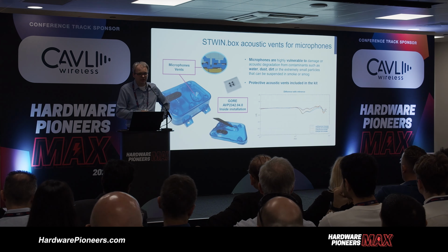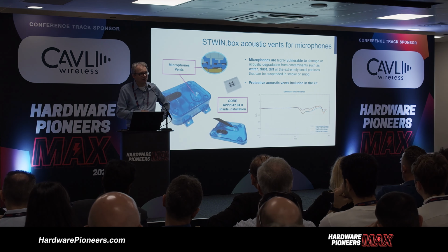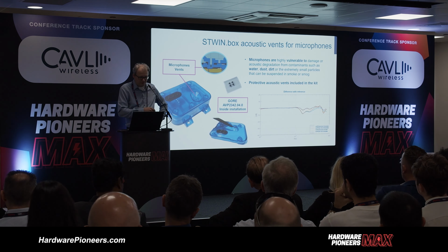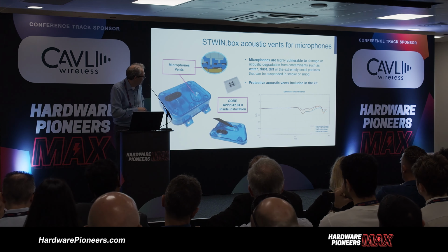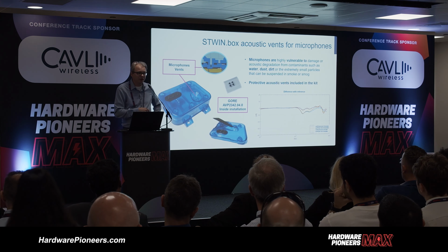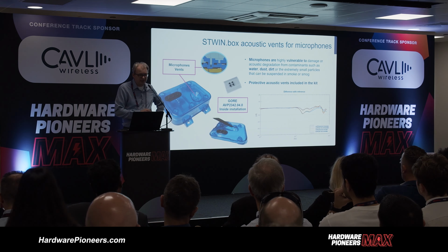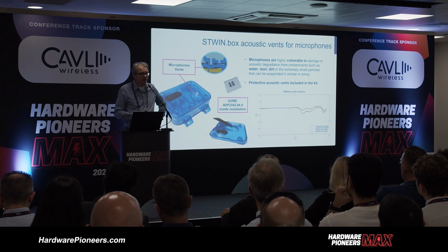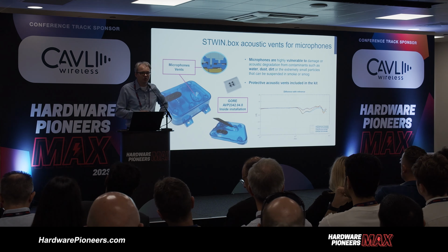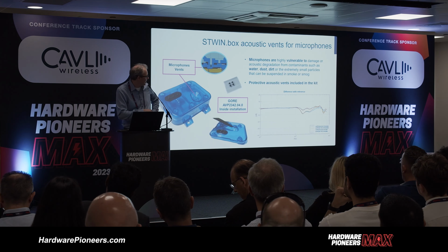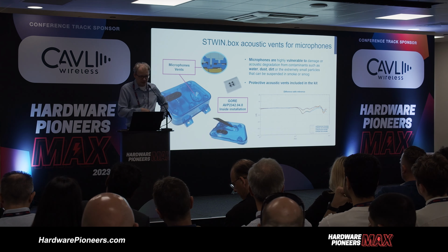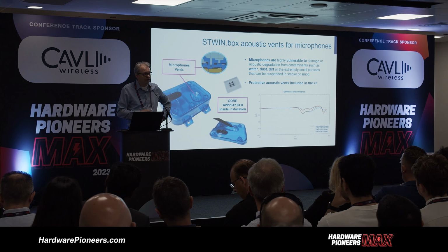Another new thing on this development kit is for the microphones and pressure sensor, that we included this kind of protective acoustic vents. These are coming from company Gore, so a bit similar to what you use in different kinds of fabrics. But what we did is that we measured this up to 80 kilohertz now and verified that it works up to ultrasound. So again, something that you would need to take into account in the final end product design to ensure that the dust and water is not entering all the way into your end product. And this type of Gore membrane would fit very well then for the microphone use cases.